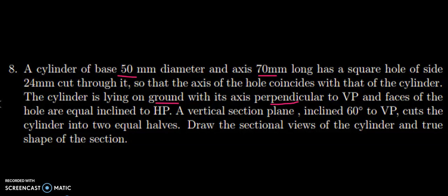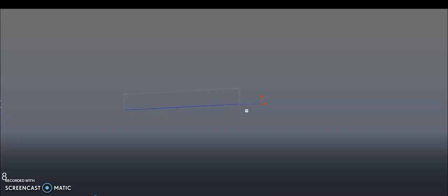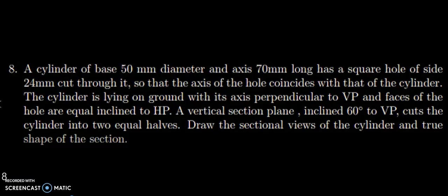Cutting plane is actually inclined to VP, perpendicular to HP. It's inclined to VP by an angle 60 degree. So this is the question, and we have to get the orientation. It should be like this.